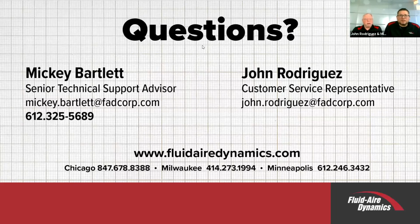So we have a couple questions. What's the convenience of air pressure regulators? Well, air pressure regulators are point of use typically. There's also what's called an IC or expander that's placed right after that dry tank. That's kind of gone away. If you buy a variable speed air compressor, those types of regulation aren't needed any longer. But you need to regulate. There are some machines that need 100 PSI, some that need 90 PSI, and some that need 60 PSI. So you need to have the regulators at those locations.